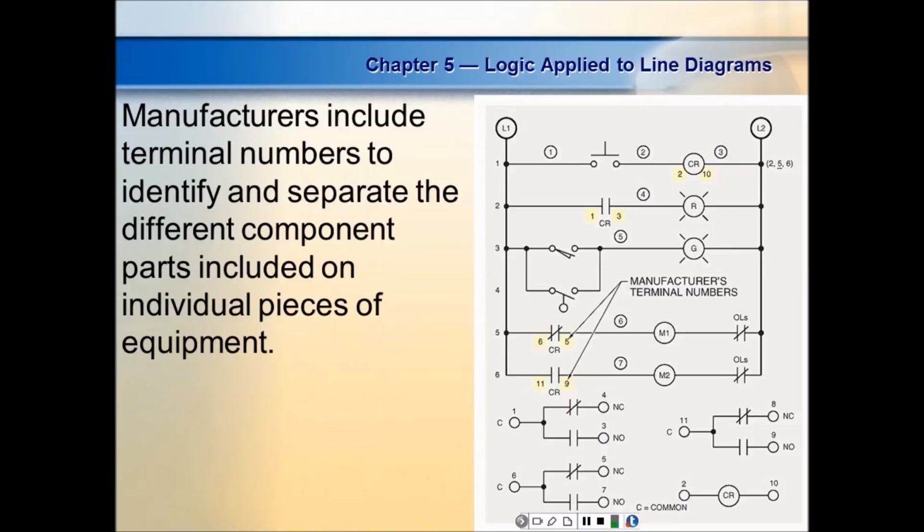If I come back there and you've got something wired up, it would be almost impossible for me to figure out how you wired it, unless you've got what? The manufacturer's number. Now I can look and see a wire that's supposed to go between 6 on this to 4 on this, right? You understand? And it makes it real fast for us. Also, it helps you troubleshoot.